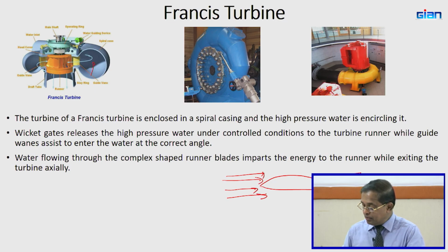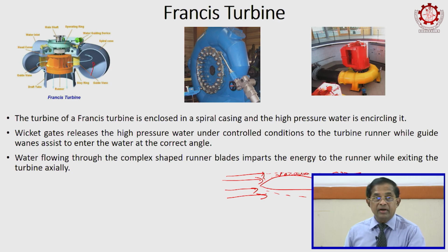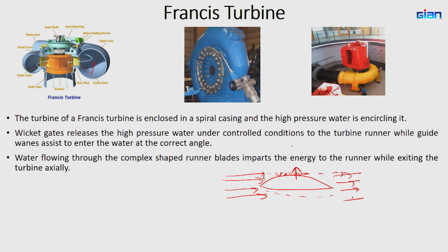So they have to leave the same way. Therefore, on this side the speed is faster, and on this side slower. Then there is a vacuum effect here, so it will be lifted, or on this side there will be a force. The blades have been shaped in this way, so when the flow goes on one side, there will be a force for the rotation.